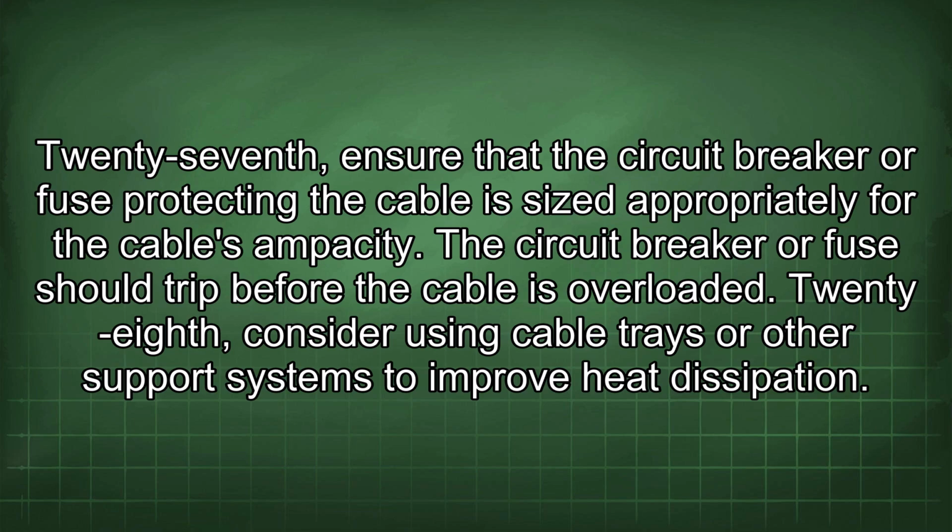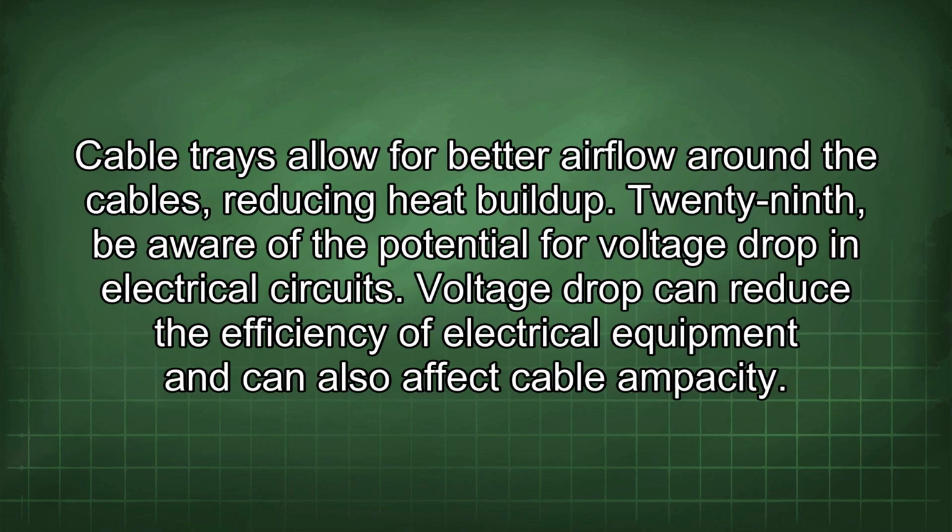28th, consider using cable trays or other support systems to improve heat dissipation. Cable trays allow for better airflow around the cables, reducing heat buildup. 29th, be aware of the potential for voltage drop in electrical circuits. Voltage drop can reduce the efficiency of electrical equipment and can also affect cable ampacity.